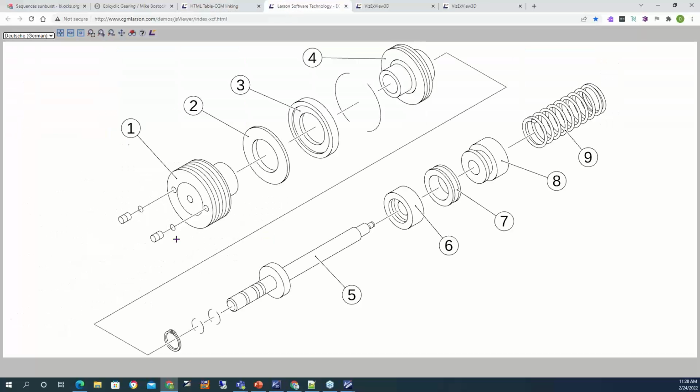The other example we have here is, again, a CGM file, slightly different toolbox. So you could introduce your own toolbox. And this has what we call a companion file. So CGM can have XML companion files, and we could easily switch between those to give us different information. So if we hover over here, we have the assembly. So we have kind of English, and then we could say, I now want to look at the German companion file. We move over and we see the translation.